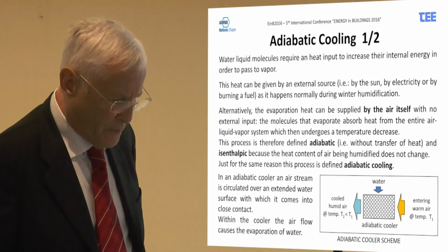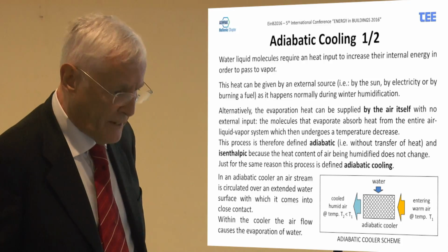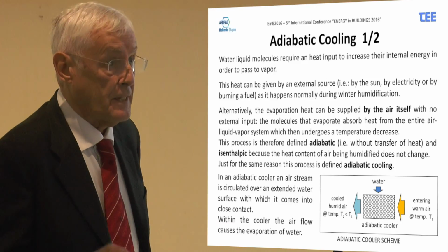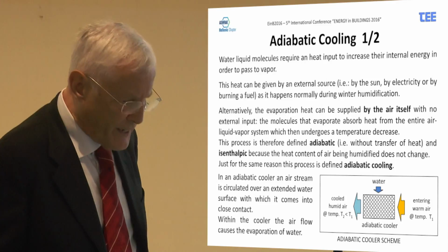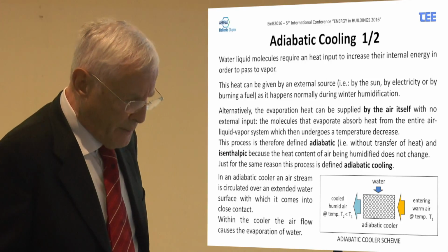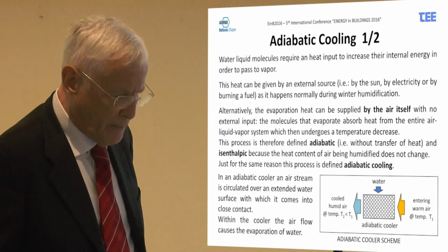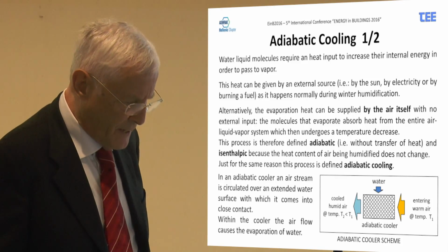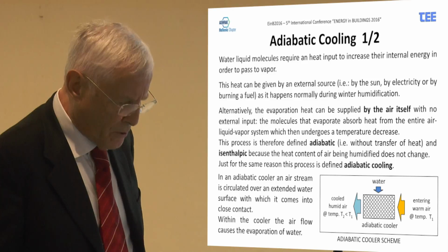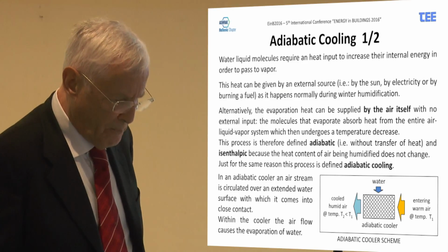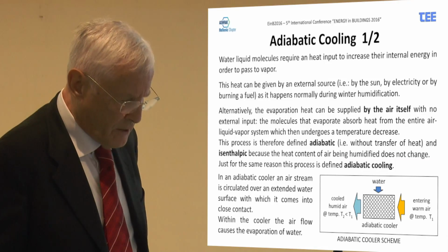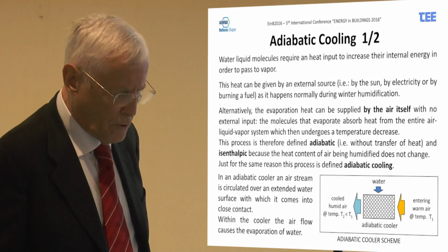The molecules evaporating absorb heat from the entire air-liquid-vapor system, which then, to supply this energy to the vapor, will decrease the temperature. The process is therefore defined as adiabatic, which means without transfer of heat, and is isenthalpic because the heat content of the air being humidified does not change. Just for the same reason, this process is defined as adiabatic cooling.